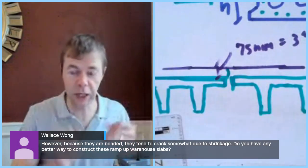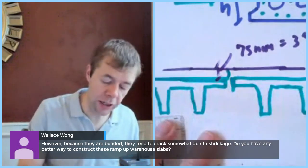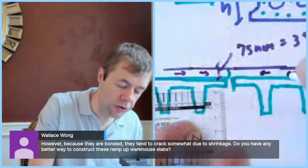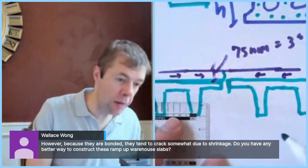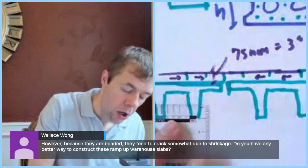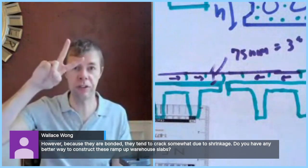But there's more, just like Wallace said. This very, very thin slab is going to try to shrink. It's going to try to shrink inwards and go this direction. Shrink inwards and go this direction. And then that again is going to have the same problem that I drew before, and that's going to cause cracks to want to form here. Okay, so those are two different distinct things, Wallace, two different distinct things.